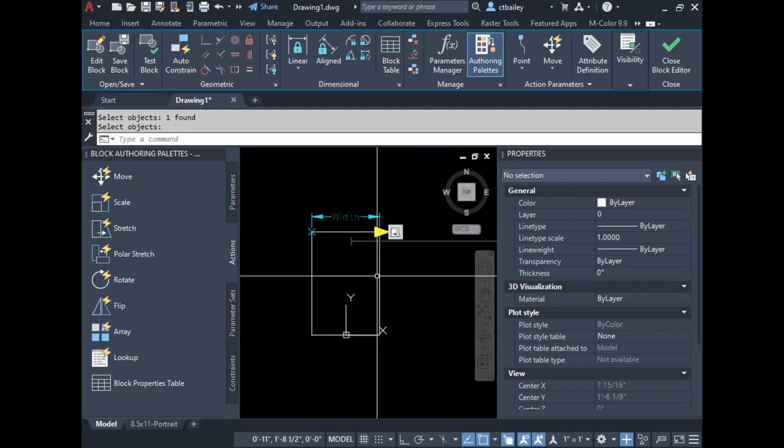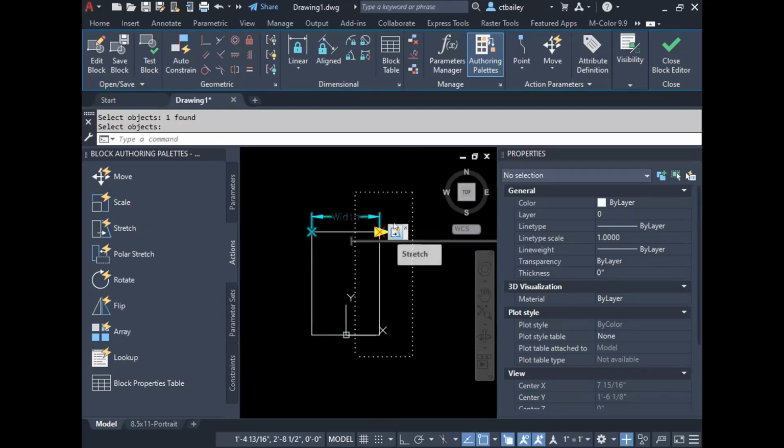So what did you select for the dotted line? I mean, what is that difference? I'm going to make it stretch. Oh, you're stretching, that's right, I forgot. The dotted line is important on the stretch action because it slices through that horizontal member. It slices through this horizontal member. And this segment here is wholly contained within. Anything that's wholly contained within that box is going to be moved. Anything that's sliced by that box is going to be elastically stretched, like my gut.